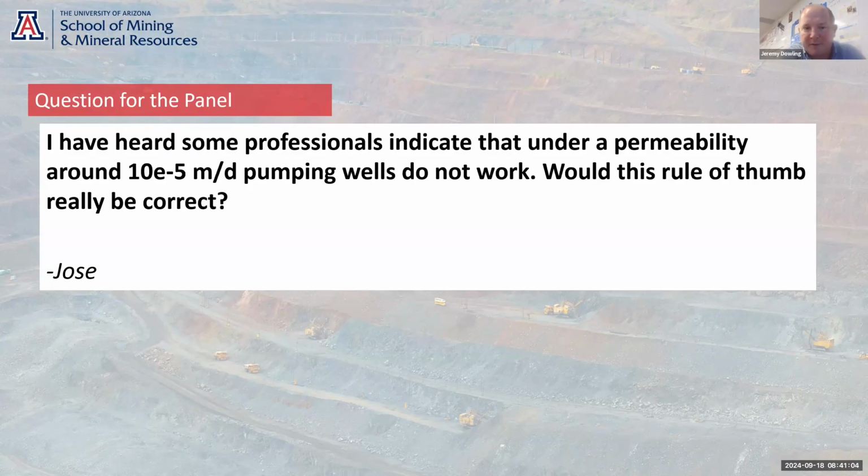So as much as the permeability values themselves, the interconnectedness of the fractures and the extent of the fracture network is also very important for determining the performance of production wells for mine dewatering purposes.